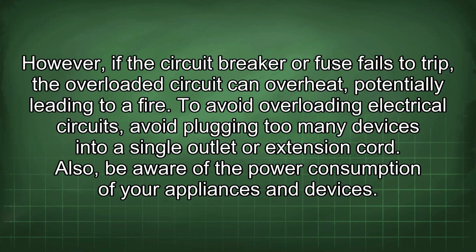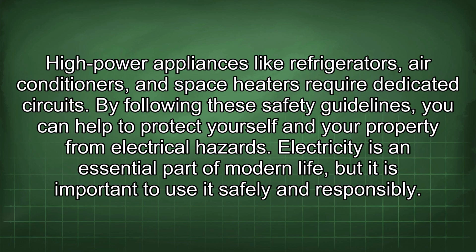To avoid overloading electrical circuits, avoid plugging too many devices into a single outlet or extension cord. Also, be aware of the power consumption of your appliances and devices. High-power appliances like refrigerators, air conditioners, and space heaters require dedicated circuits. By following these safety guidelines, you can help to protect yourself and your property from electrical hazards. Electricity is an essential part of modern life, but it is important to use it safely and responsibly.